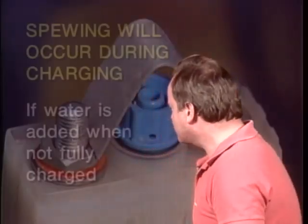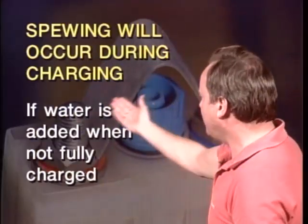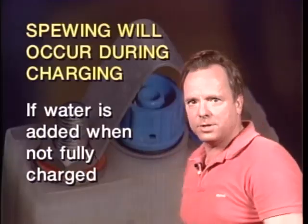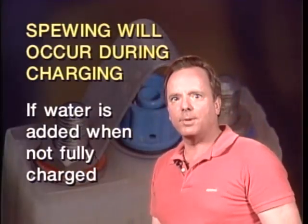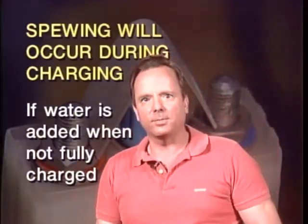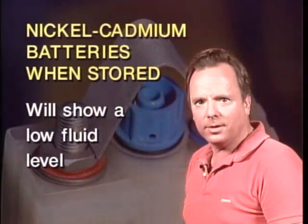Okay, now, remember we said earlier the level in a NiCad battery is lowest when it's discharged. So what would happen if you add water to a NiCad battery when it's not fully charged? Well, the answer is you'd have spewing, excessive spewing, the FAA says, because the level automatically comes up when it's charged and then you could spew it out. Because at the end of a charging period, a NiCad battery tends to put out some gas. Nickel-cadmium batteries, which are stored for a long period of time, will also show a low fluid level, and you need to know that.